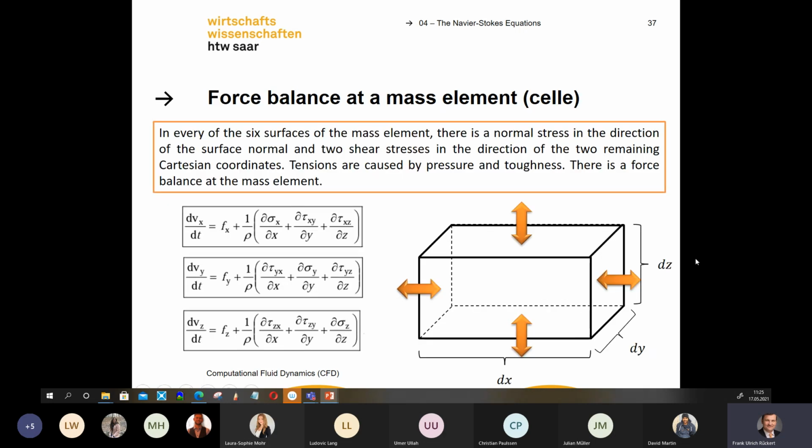Okay, and last but not least, we have to look at the forces. That's also something you must know. If you remember your wing, you want to calculate the pressure field on your wing, you want to calculate the forces, the drag force or the lift force. You can solve this with the different shear stresses, and the shear stress added to the force is the derivative of the velocity. So more or less, I summarize, you need the viscosity to calculate the forces on the walls, if a fluid goes over a wall, over the wing for example, with a defined velocity.